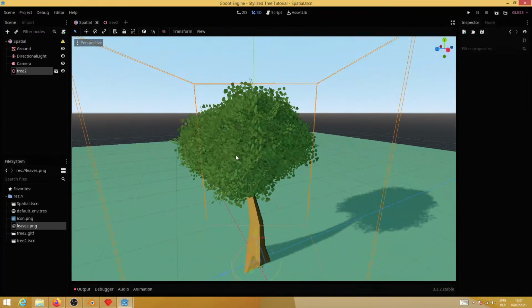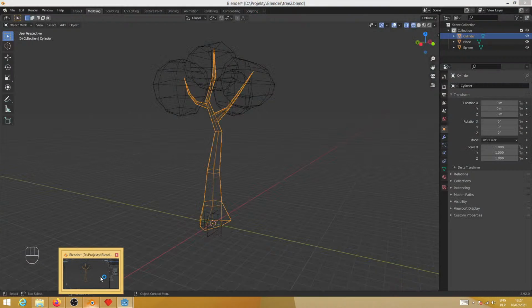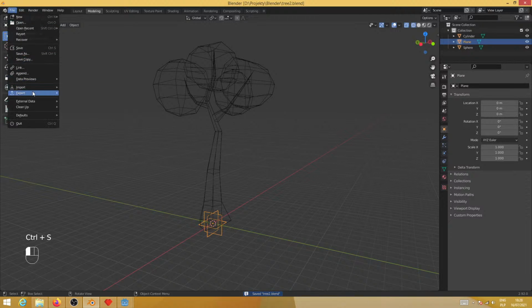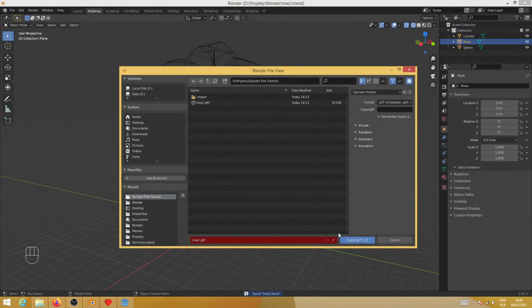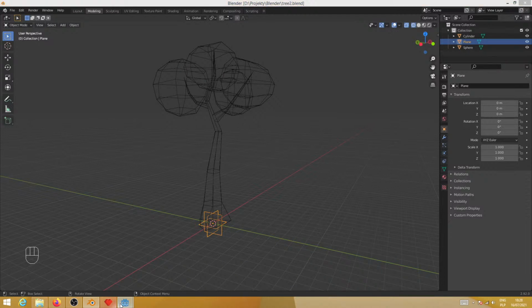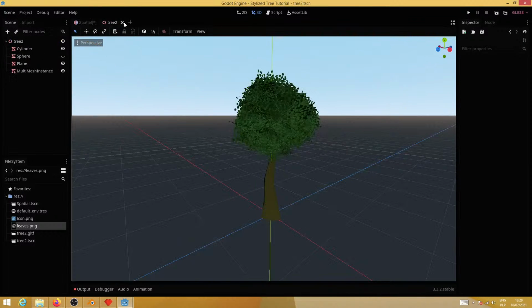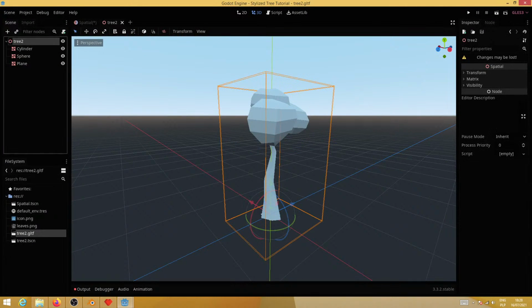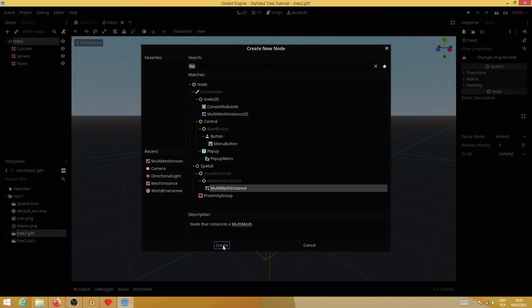The other thing you can do also is to set the shading in Blender for the leaf mesh to smooth, which I hadn't done. So let's do that quickly. So here, let's also shade smooth. Let's save it and let's export it again. I will probably need to set it up quickly yet again. So let me close this one. Let me reopen this one. Yeah, I need to set it up again. So let's do it quickly.